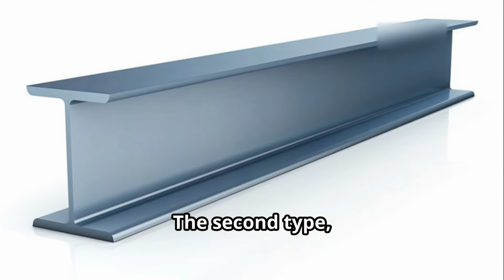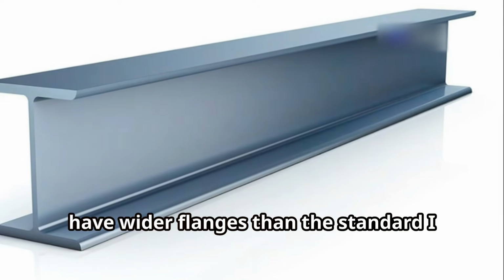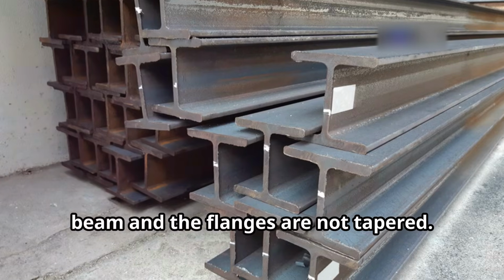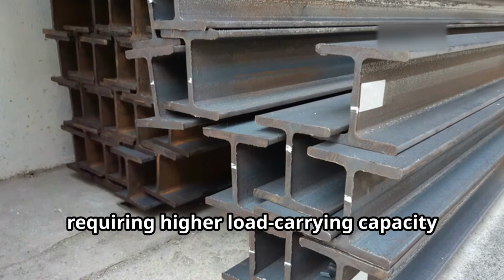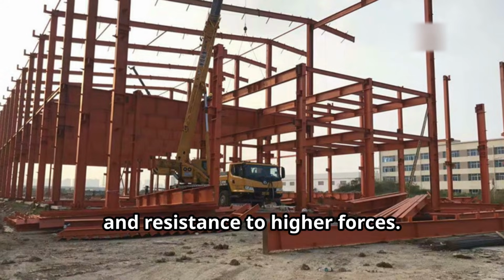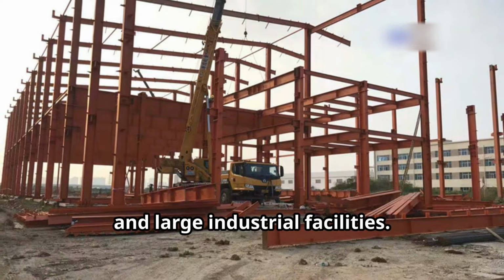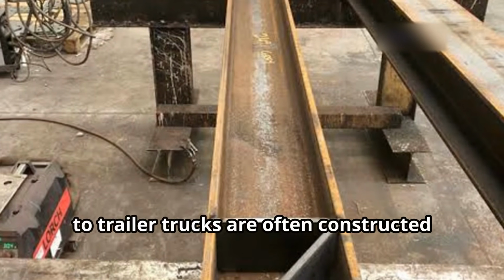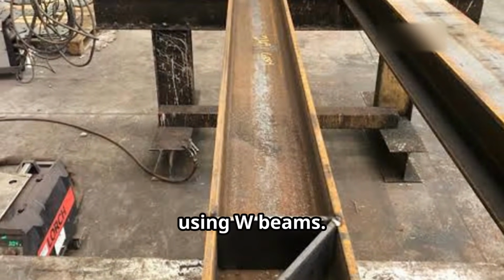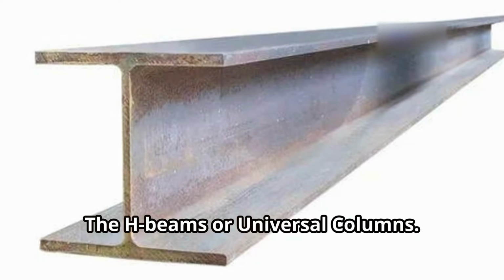The second type, wide-flange beams or W-beams, have wider flanges than the standard I-beam and the flanges are not tapered. They're perfect for applications requiring higher load-carrying capacity and resistance to higher forces. They are used in bridges, warehouses, and large industrial facilities. The main chassis of certain heavy machineries, such as huge blast hole drills to trailer trucks, are often constructed using W-beams. And here comes the last one, the H-beams or universal columns.